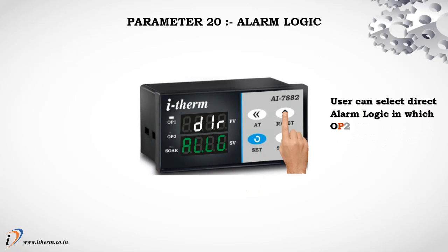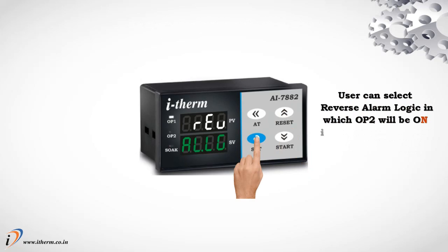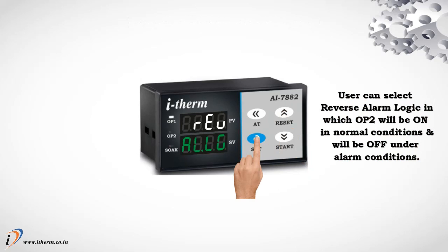Parameter 20, alarm logic. User can select direct alarm logic in which output 2 will be on under alarm condition, otherwise off. User can select reverse alarm logic in which output 2 will be on in normal conditions, and will be off under alarm conditions.